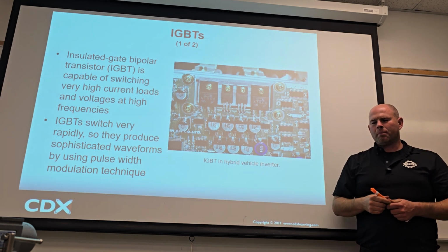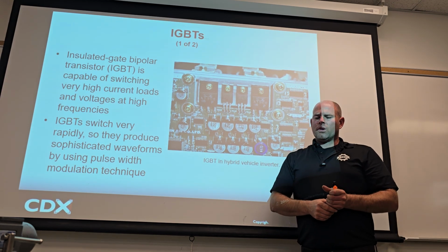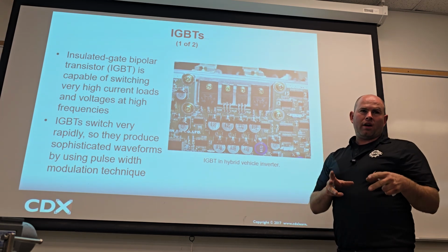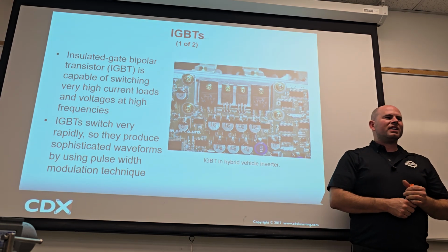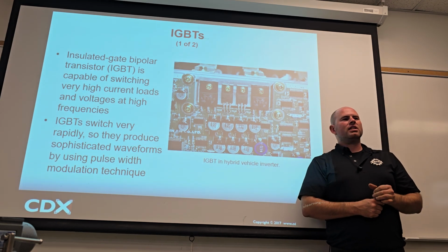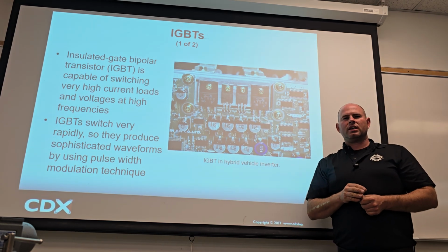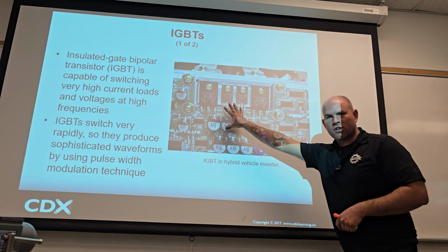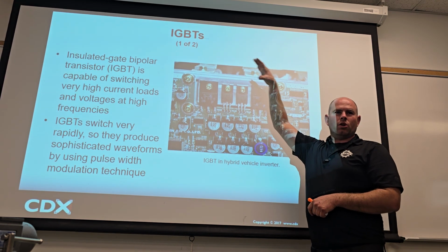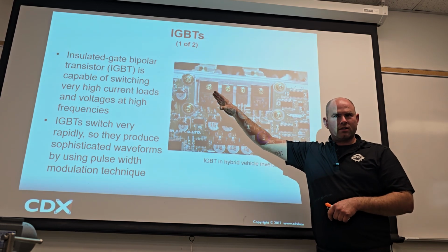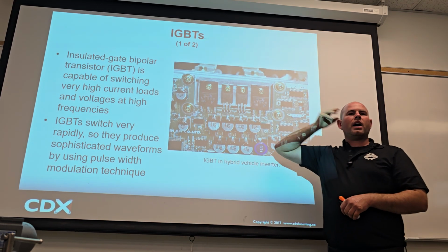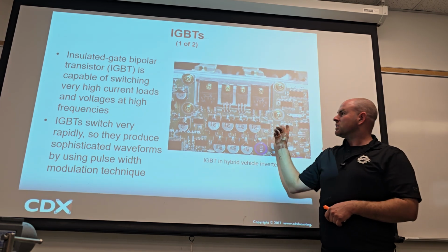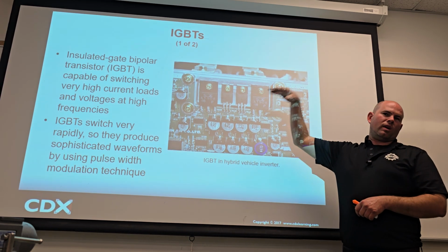So it does happen, but the fact of the matter is, you guys aren't really excited about hybrids, I can already tell. Let's say even a brand new hybrid comes in, all anybody's asking you to do is, is it the inverter? Is it the wiring? Is it the motor? See what I'm saying? That's it. So your knowledge should be knowing enough to determine if it's the inverter, which means this whole circuit board, is it the wiring, or is it the motor?